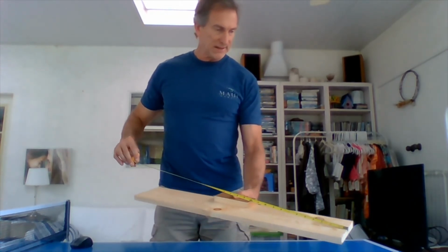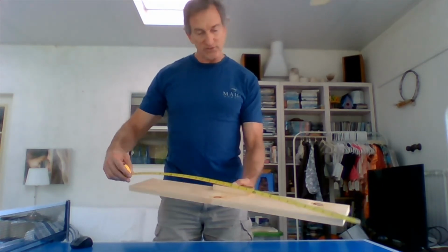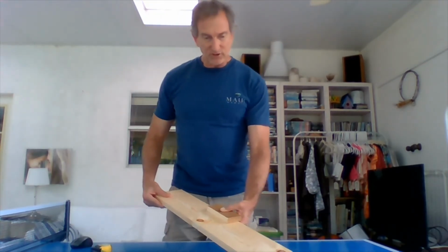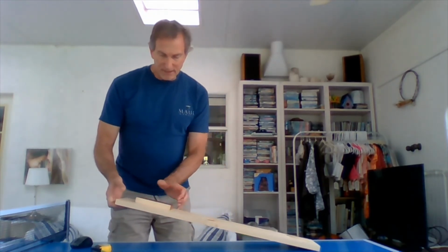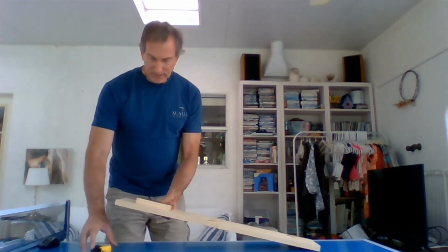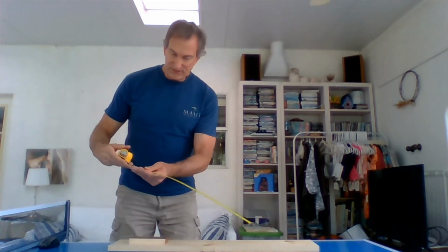The length of our ramp here is measured at 31 inches. I'm going to place our ramp right here and increase the angle a little bit at a time until we start to get slippage. We'll record that height, and then later we can figure out the angle, and from that we can determine the coefficient of static friction.